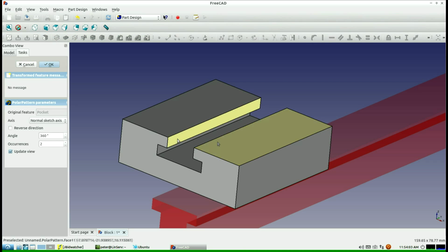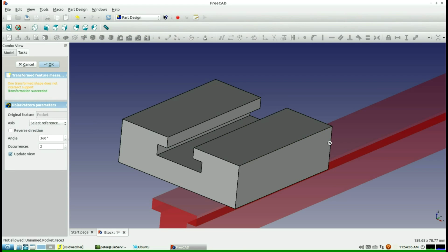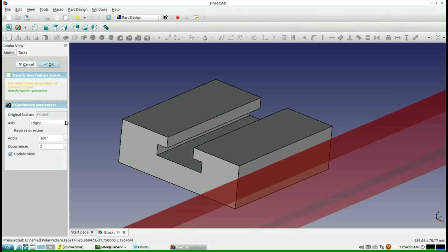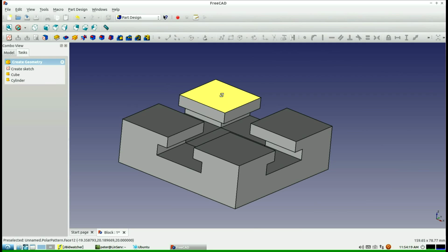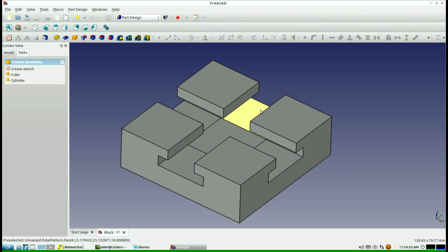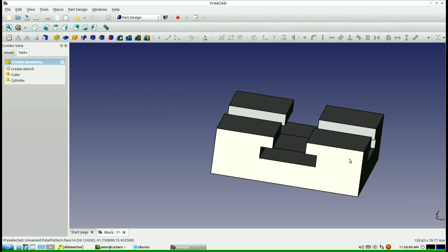We can then revolve this around a common axis, and we'll select the one in the back right-hand corner, and we'll revolve it 4 times. And what this will do is now whatever we do to that very first sketch we did, it will demonstrate it on the next pattern. So now we've created the base block for our double crank slider. It's interesting to note that we can't 3D print this.